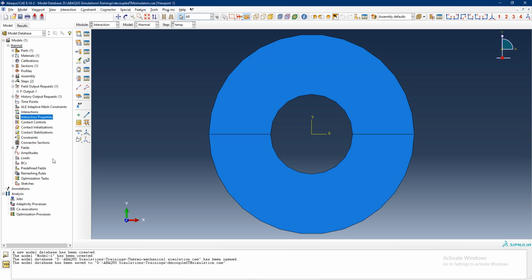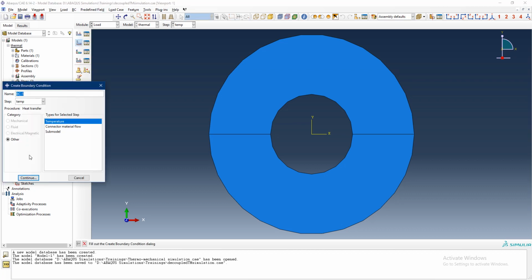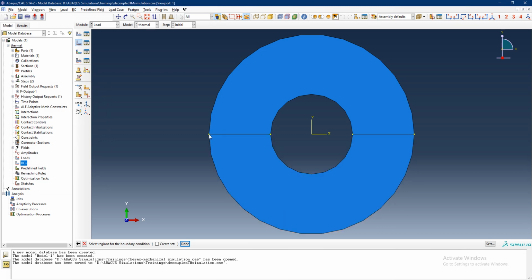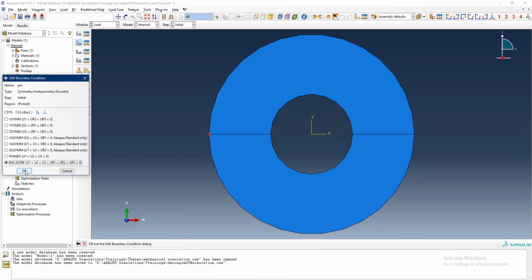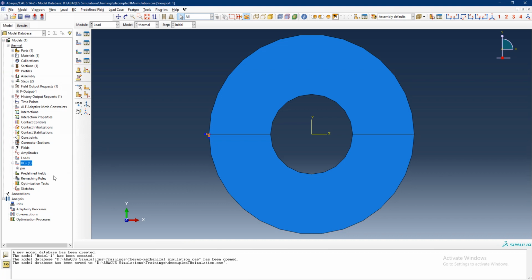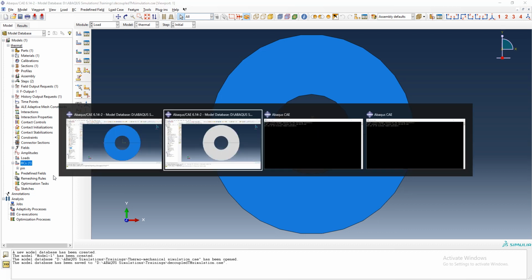What I would also like to do is pin it from some place, mechanical, and then pinning. So I would like to pin it from here, let's say, and then what we need to do is define loads, and we need to define the film conditions. This is something which I will look in the other simulation model, and then we'll define it here.